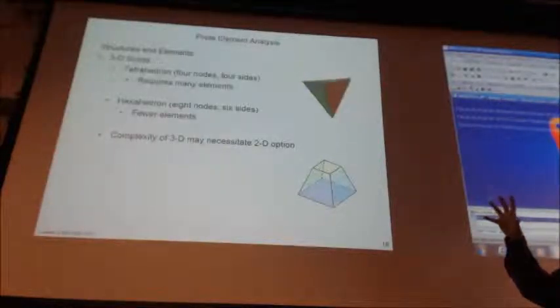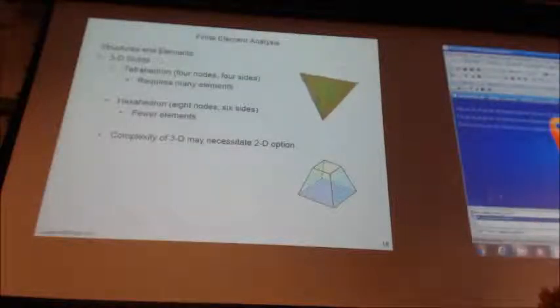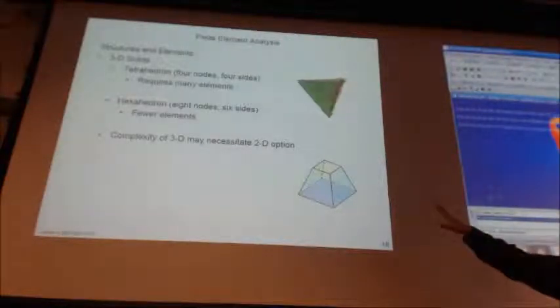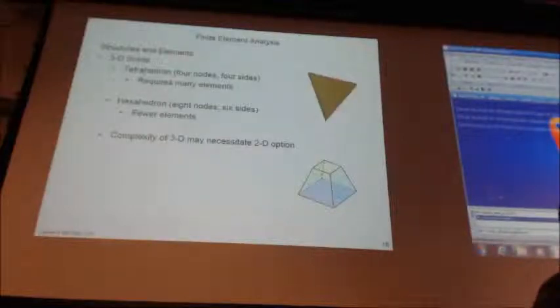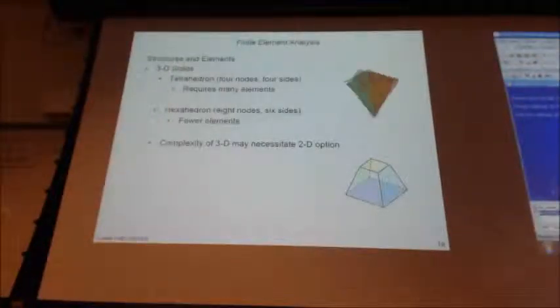And the triangles tend to be a little more conservative than if you're using a hexahedron or even just a quadrilateral, 2D four-sided square. So, I think I used the tetrahedron on this bracket. I mean, they're okay to use. It's not like you don't use them because they produce conservative answers, but that's just one thing you have to be aware of when you're using that shape for your 3D models, is know that it's going to probably tend to be on the conservative side, and that's okay.